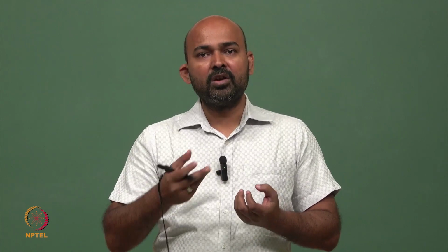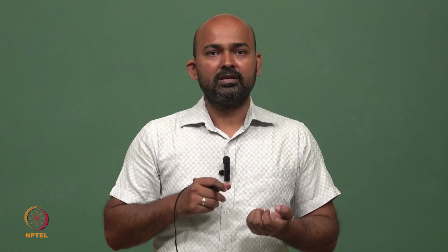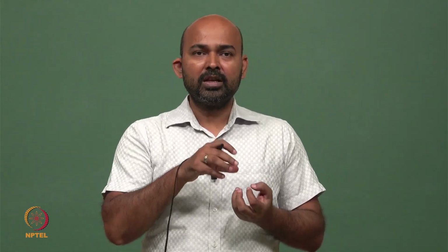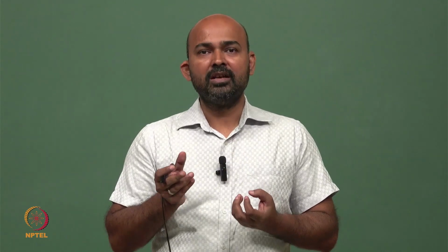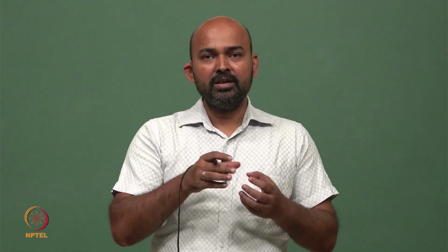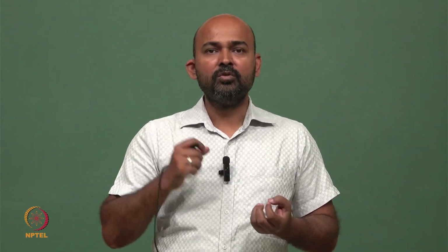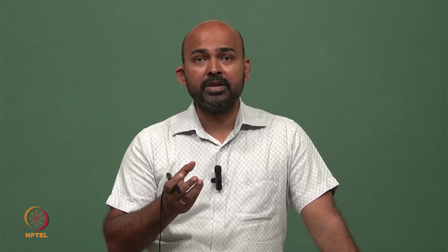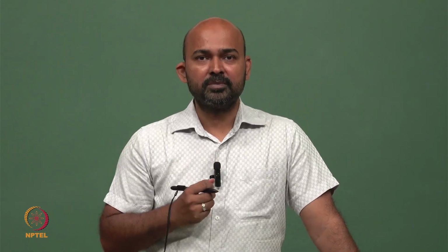For example, this is 1 watt of power which is generated in the chipset, or it is 2 watt, or it is 5 watt. Depending upon that power dissipation, we need to design the heat sink. If the power dissipated is more, we need bigger and bigger heat sinks to remove the heat. And we also should know the maximum junction temperature which is allowed in that chipset.